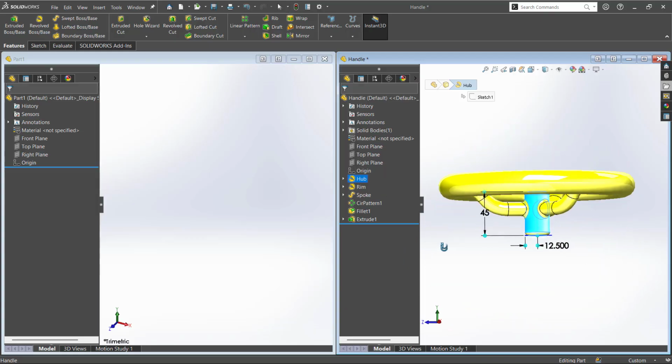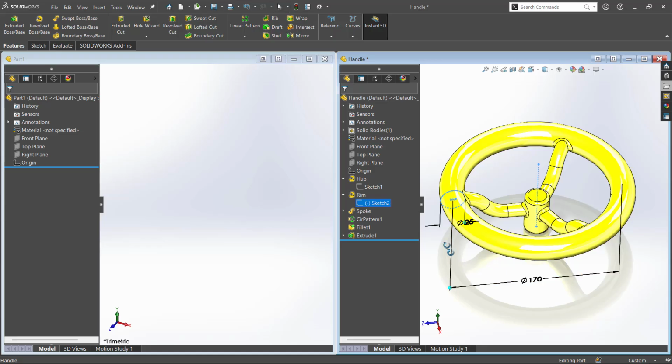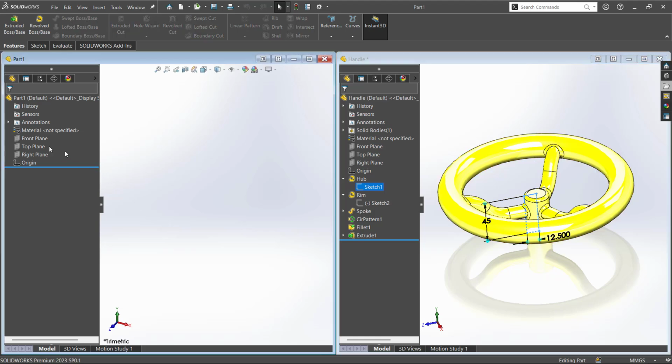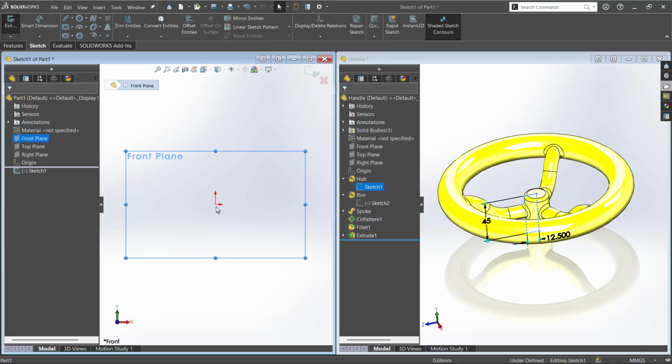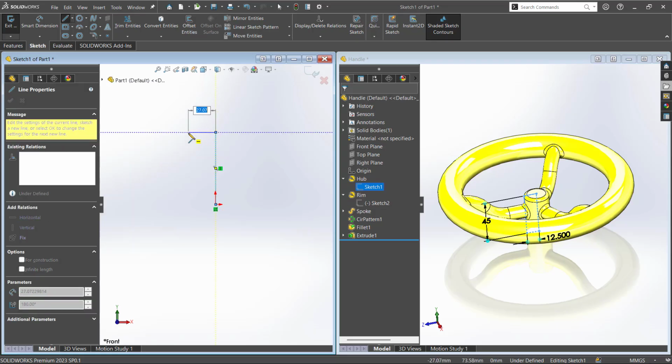I could see the first feature which he has created is this one, that is having this particular round, and the second feature is this one. In short, this is a circle, diameter 25, and this is a rectangle, again 25 in short. So instead of creating these two separately, I can create it in one click also, right? Let's do that. Just select the front view, click on the sketch, and create this rough sketch. Start with this.